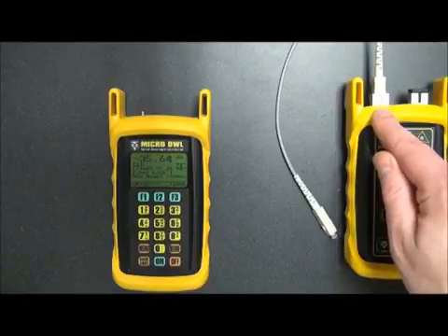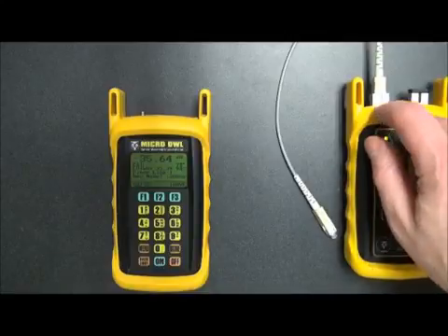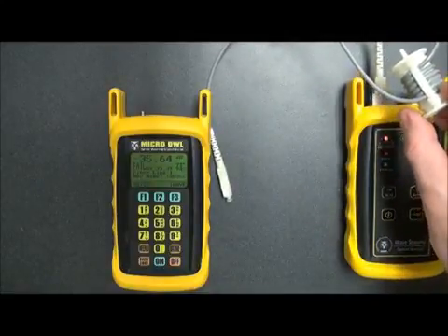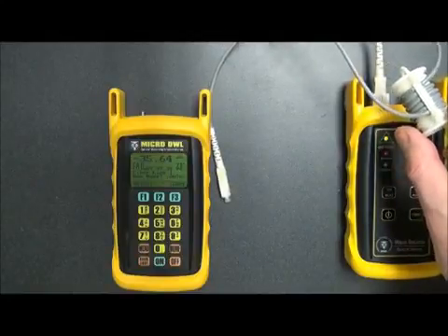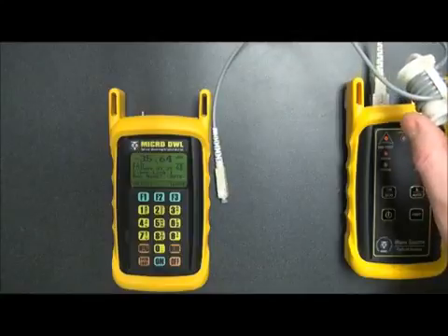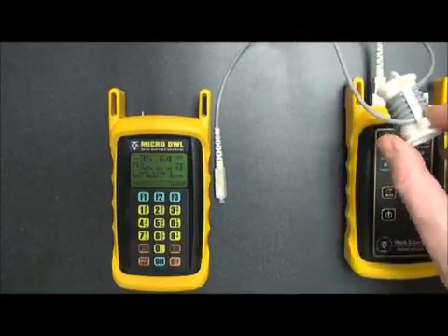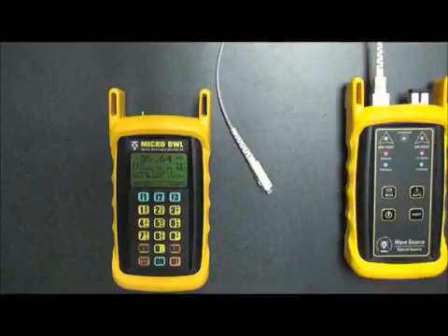You have to start all over again. The second thing, and this is specifically related to multimode fibers, is that you don't want to let the cable unwrap from this mandrel. That also changes your reference level, and if something happens to this mandrel, you will also have to start over again from the beginning. So it's really important to not disturb the mandrel and not disturb this connection here.